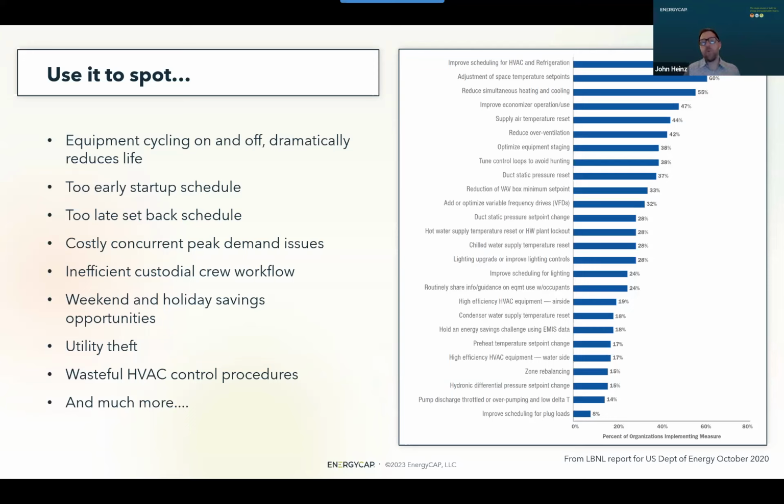It helps to keep an eye on weekend shutdowns. It also not only is looking at scheduling activities, but looking at demand charges. Many electric rates have demand values to them. And if you go above certain demand values, then you get penalized, and you're paying for it throughout the remainder of the year. So it helps keep a pulse on even demand spikes within buildings to hopefully mitigate any types of issues that would then later show up on your bills.